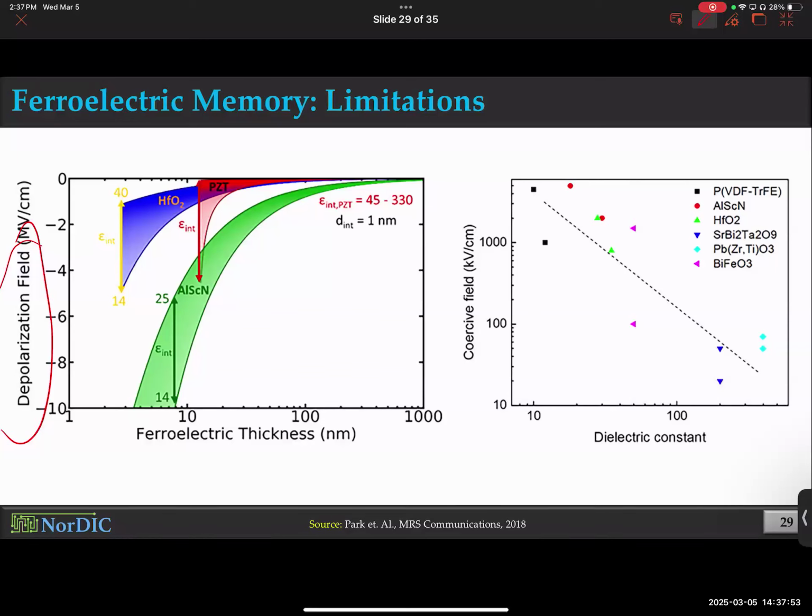What are the challenges? Other challenges. We have seen some challenges. Some other challenges would be depolarization. I keep using the term depolarization. So when you polarize a ferroelectric, make it positive polarization or negative polarization and let it go, it's not going to remain there forever. There is a physical process through which it will gradually relax and lose its charge. Unlike a regular capacitor that loses charge almost immediately, in milliseconds, it will take several years, right? But it will still depolarize, okay?